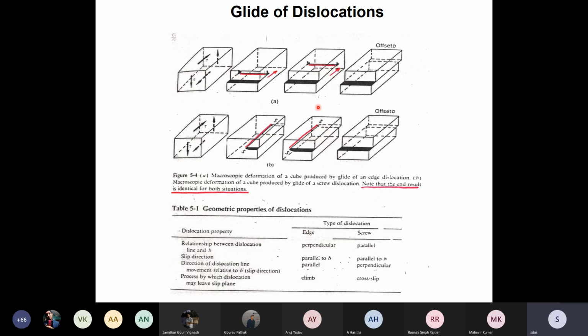For each dislocation, Burgers vector is perpendicular to the dislocation line. What does it signify? Dislocation line and Burgers vector perpendicular to it, so it defines a surface. So when an edge dislocation glides on a 111 type plane and comes near another intersecting 111 plane, it cannot move from one slip plane to another.